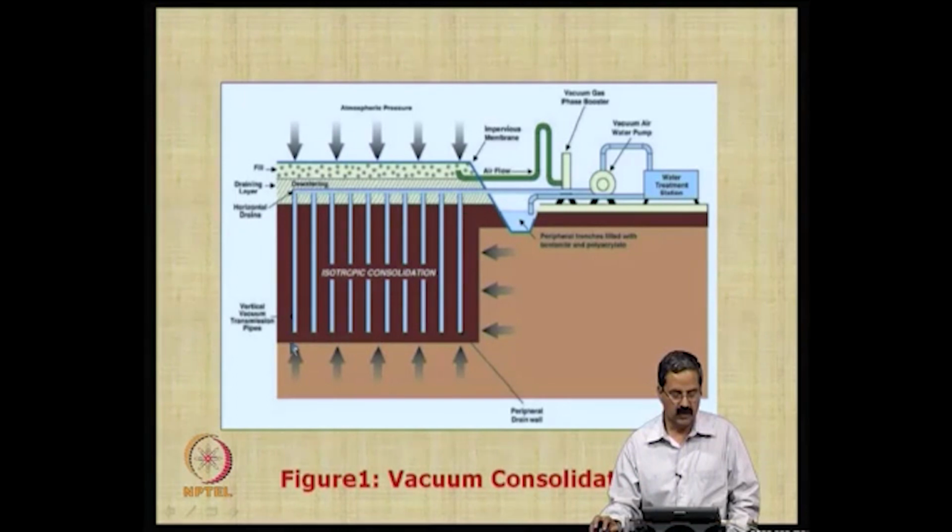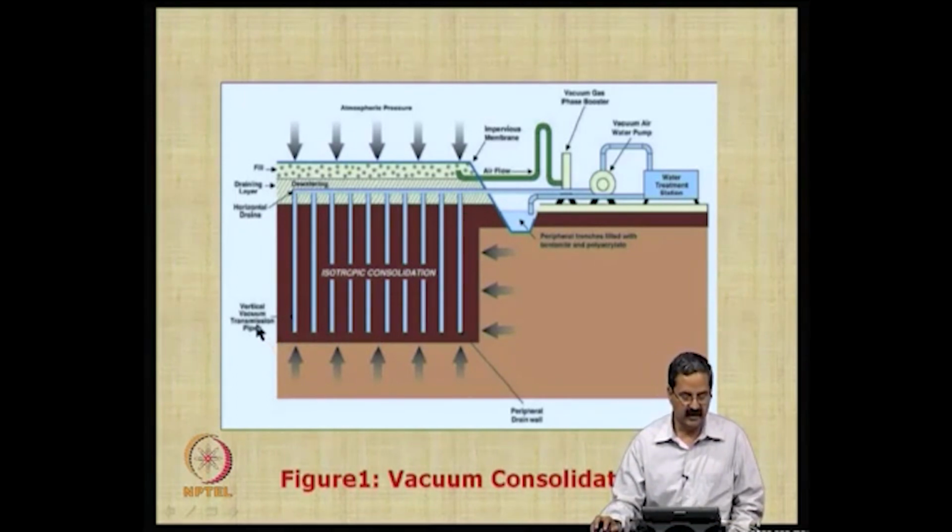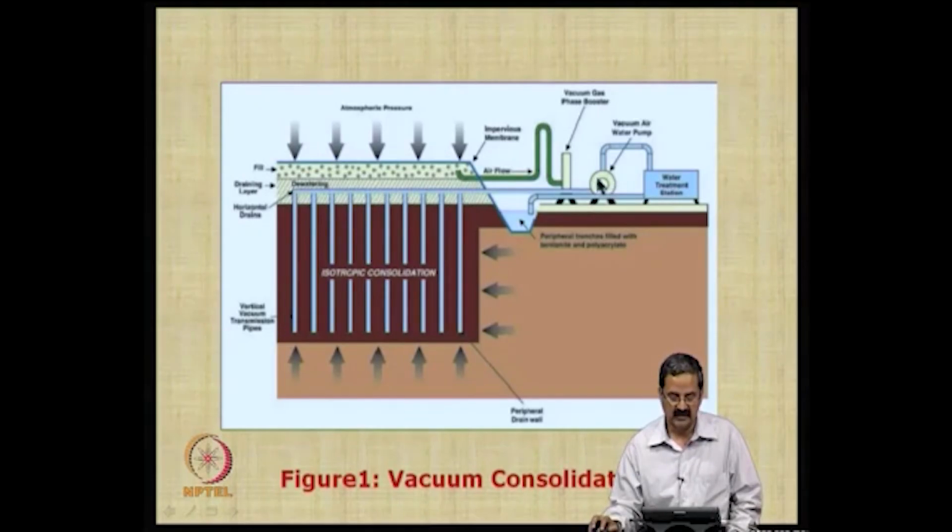So, what we do here is that we are creating the vertical vacuum, there are the vacuum pipes, okay. Yeah, they are all connected, and this is a vacuum air water pump, vacuum gas phase booster. So, there is some more additional arrangement. In fact, you are trying to increase the effective stress in the fill also.